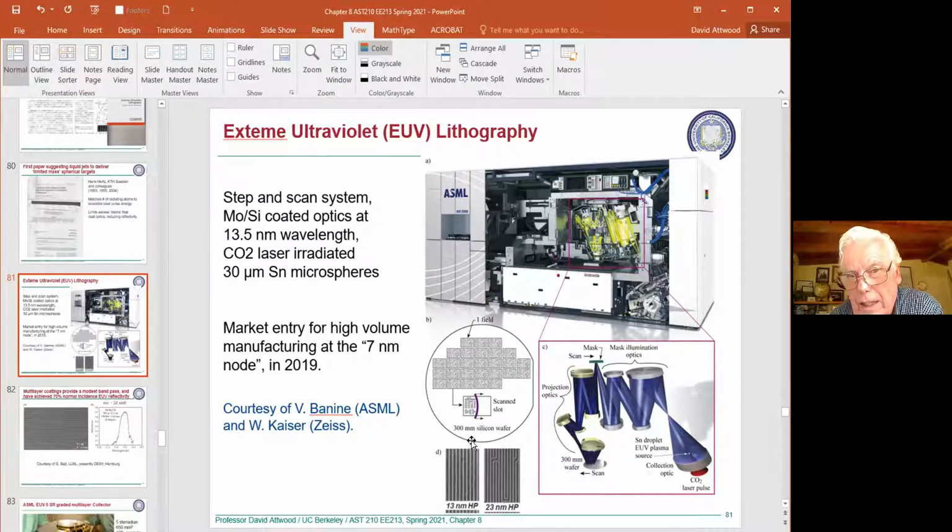And this is what they mean by scanning. The optics don't image. There's a mask pattern. Let me start with that. So the laser pulses down in the basement, comes up. There's some optics which take that radiation and shape it into a narrow curved slit of light radiation, which comes up and it hits a mask. So what is the mask? The mask is a flat substrate with a pattern on it, an absorbing pattern.